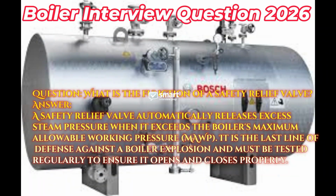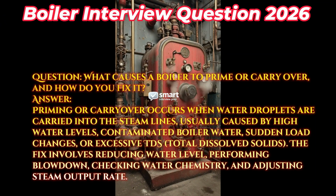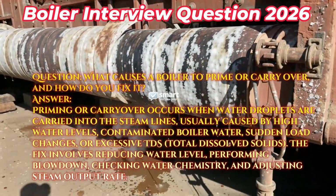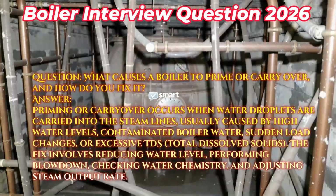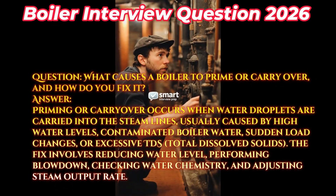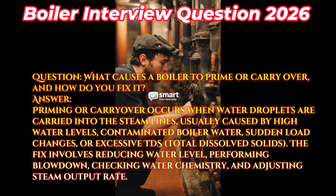Question: what causes a boiler to prime or carry over, and how do you fix it? Answer: priming or carryover occurs when water droplets are carried into the steam lines, usually caused by high water levels, contaminated boiler water, sudden load changes, or excessive TDS, total dissolved solids.